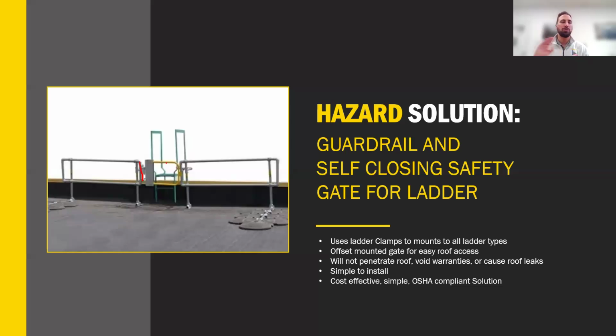There's nothing more frustrating than climbing a ladder and at the top of that ladder is a gate about to hit me in the face. It has to be mounted to the railing, so there's room for me to transition my body onto the roof and just walk through the opening. My body should push open the gate. I shouldn't have to touch a gate with my hands at all. It closes behind me. I don't have to wrestle with it. It's not pinching my fingers. That is a properly designed access point at the top of a fixed ladder as compared to just a gate clamped to the top of the ladder. If you've ever dealt with it, you know exactly what I'm talking about. It's dangerous, honestly, but it's very frustrating.